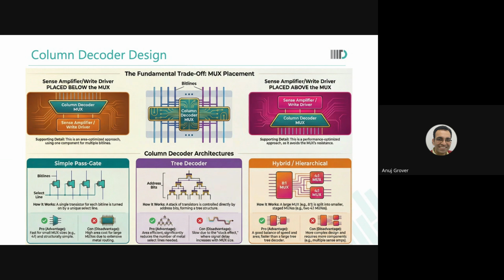We could use two sense amplifiers. Your question was, do we need? I said no, you don't need. You could use, no one stops you. But is it needed? No, it is not necessary. After the first level of decoding, I could just have the same design as the tree decoder, and the pass gate would relay across the next stage also. Even then, what have I done? If it was mux 8, instead of a stack of 3, I now have a stack of 2 only. But if you really want speed, you could put a sense amplifier there and then use a digital mux afterwards.